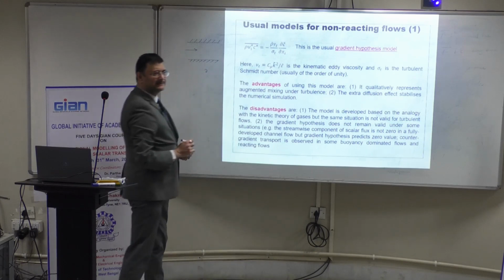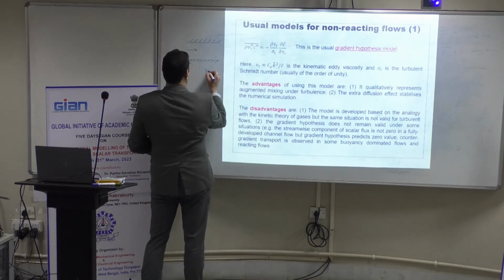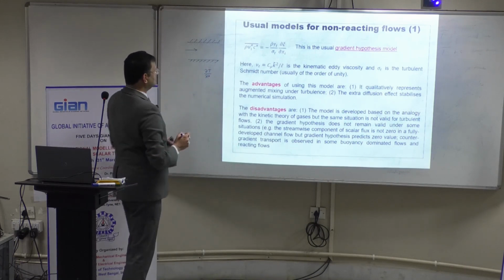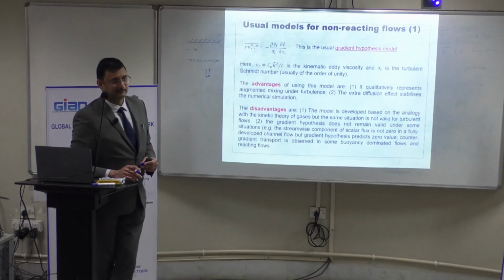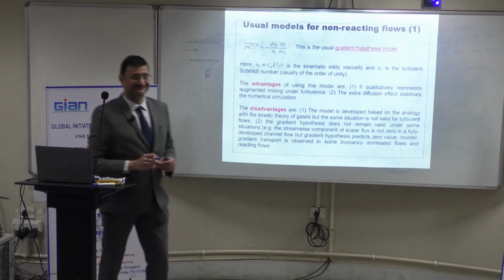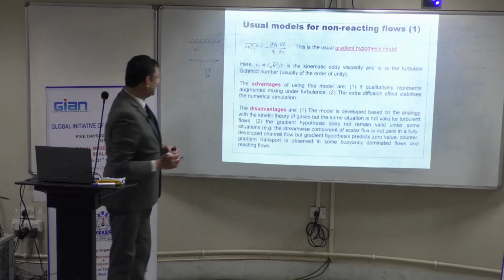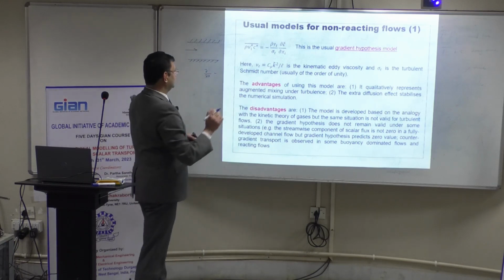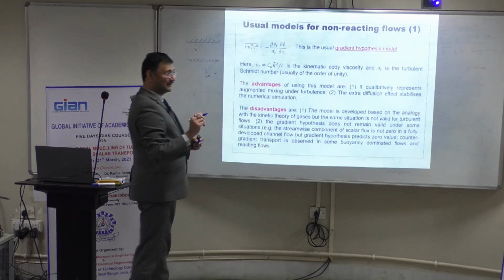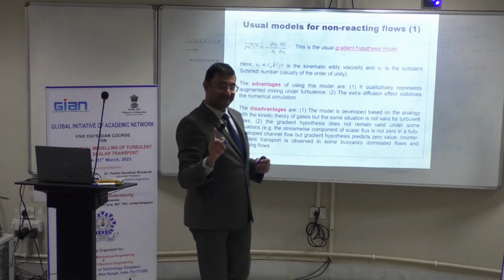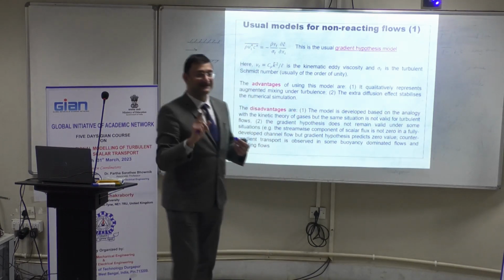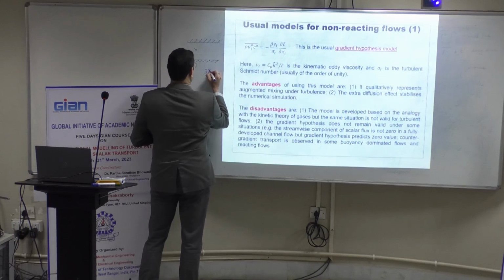If it is fully developed, what is going to be the del T del x? No? Sure? Okay. I would not say temperature, let's say some other kind of species, because temperature is not necessarily equal to zero. If I actually have heat flux at the wall, temperature will keep on increasing. So using temperature is problematic in that sense.